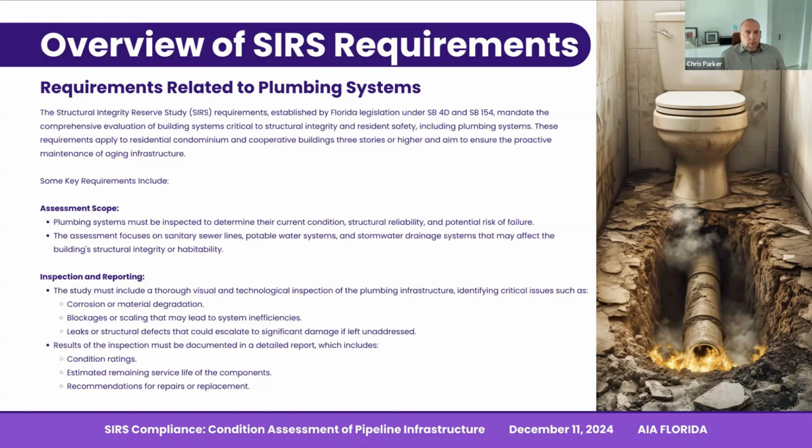So a couple more questions here, so I'm going to address those before I move to the next slide. Question: is there a benefit to still using cast iron piping in new construction? I have recently performed a project where it was spec'd as cast iron by the mechanical engineer. That's a great question. There are still a lot of industry segments that do require cast iron piping. A lot of that has to do with the fire ratings on cast iron versus a plastic pipe.